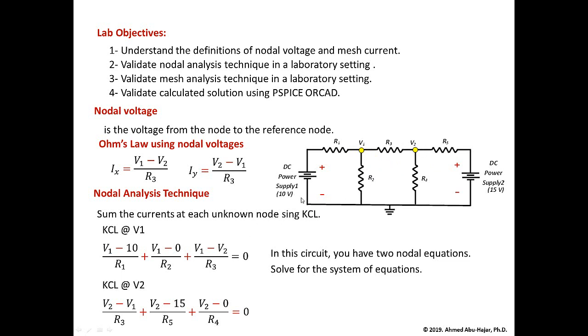In this lab, you're going to have a circuit. You're going to analyze the circuit. You're going to have the values for the nodes. Once you know the values for the nodal voltages, you can find the currents in any branch. So you can solve for the entire circuit.